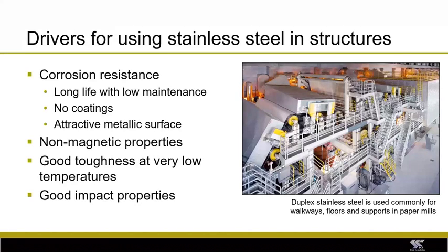On this slide, I am suggesting the reasons for using stainless steel in structures. And clearly the most common reason is if your structure is in a highly corrosive environment, or where it's important to have a long life with low maintenance requirements. Perhaps you've got an application where you really don't want a painted coating for corrosion protection, or a certain attractive aesthetic appearance is needed. Those are all reasons for using stainless steel in structures.